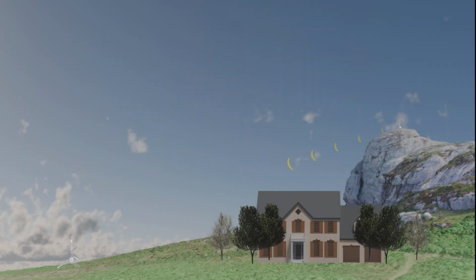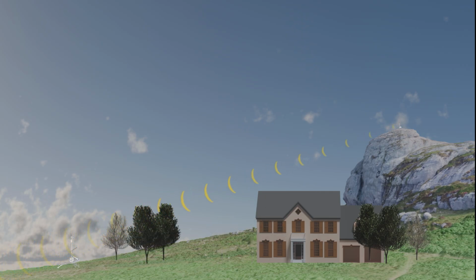With an understanding of what affects radio signal strength, the best placement for the transmitter, receiver, and antennas can be planned. Key best practices include: locate a position that gives direct line of sight. Avoid signal paths that pass through trees or heavy vegetation.